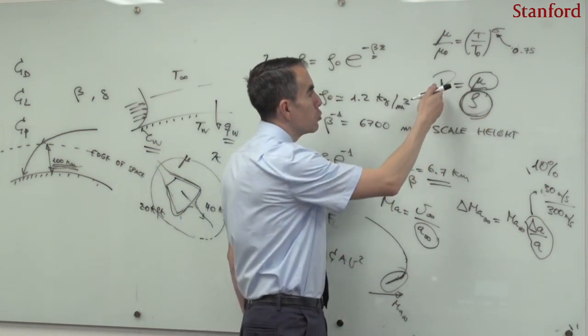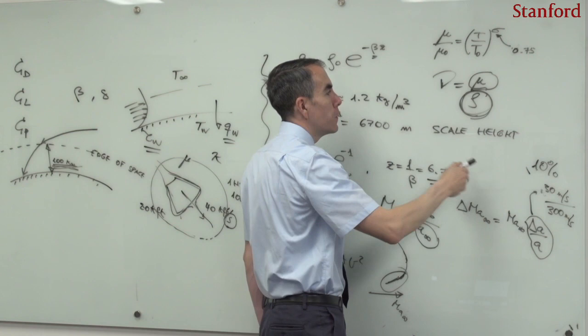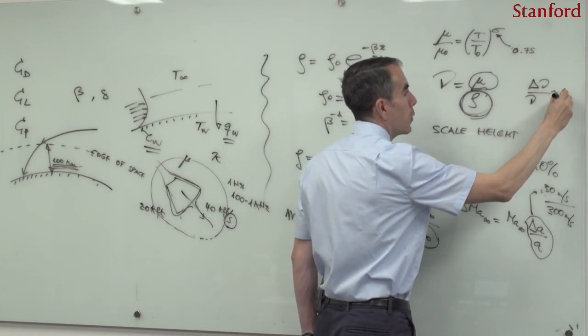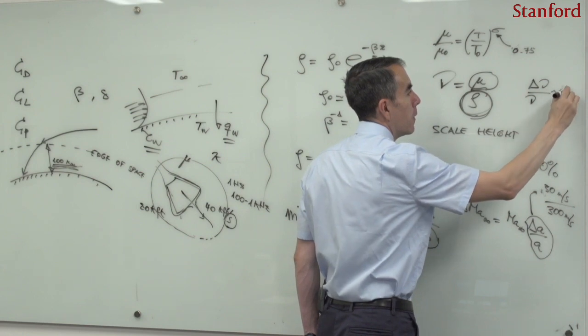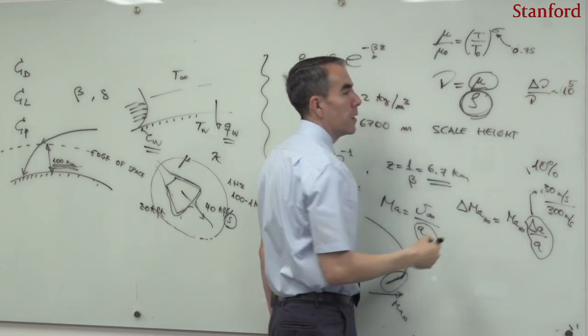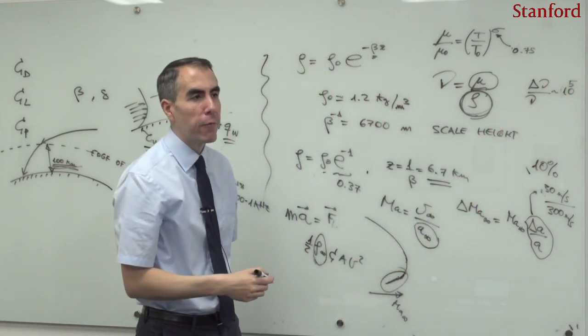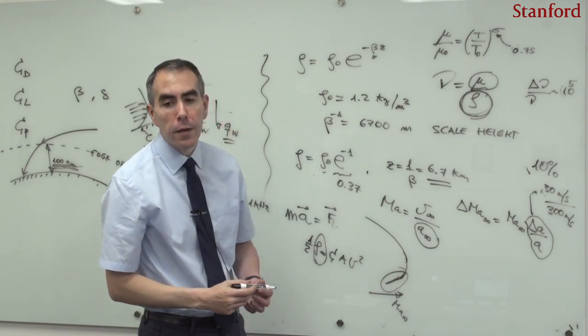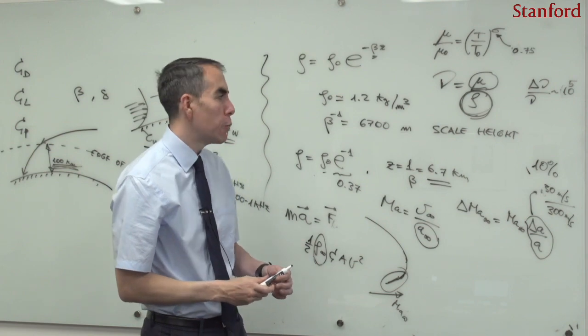And there are relative variations of the kinematic viscosity that are of the order of 10 to the 5 across the part of the atmosphere that we care for in hypersonics. So it is actually relevant in the following sense.